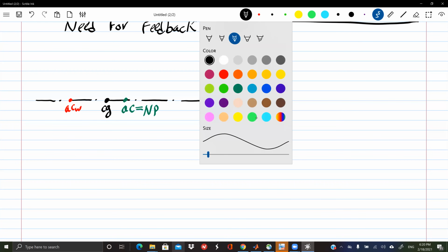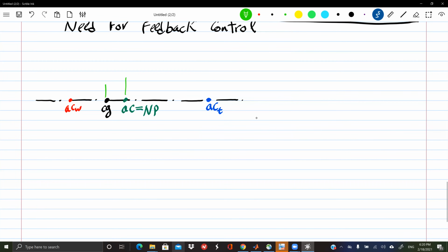And we have been obsessed with this distance. If you remember, this is the static margin, HN multiplied by C bar. Very good. So if the CG is in front of the neutral point, the airplane is stable. But remember, if it's too far from the neutral point, the airplane is too heavy. Okay? Fine. Now, I'm recalling that for subsonic flight, which we studied in the beginning of this class, the aerodynamic center is around what point? Do you remember?